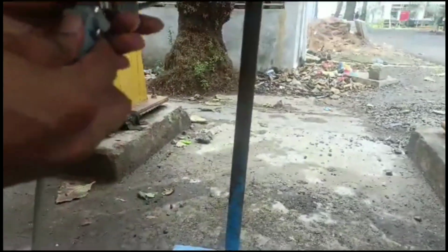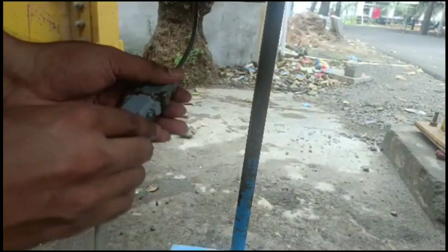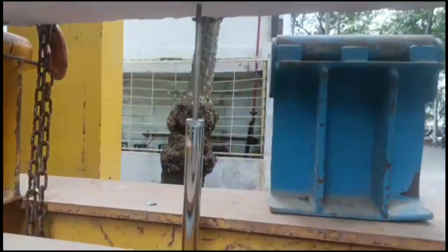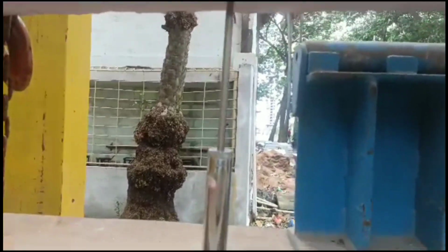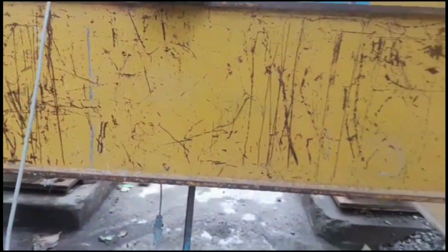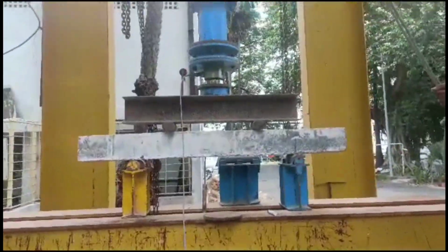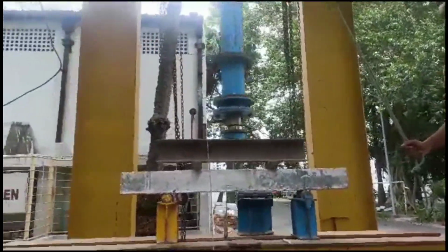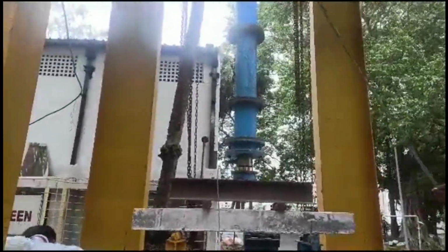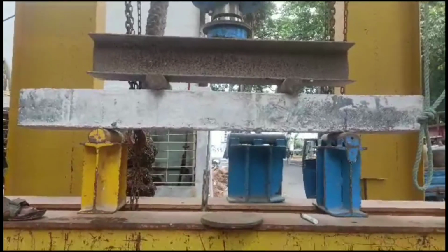The width of the crack decreased with increasing loading rates and they distributed more uniformly. The reason may be that the rapid loading rate delayed the propagation of internal micro cracks and enlarged the crack field, which caused the development of the external cracks. So more visible cracks appeared and the width of the cracks decreases with increasing loading rates.